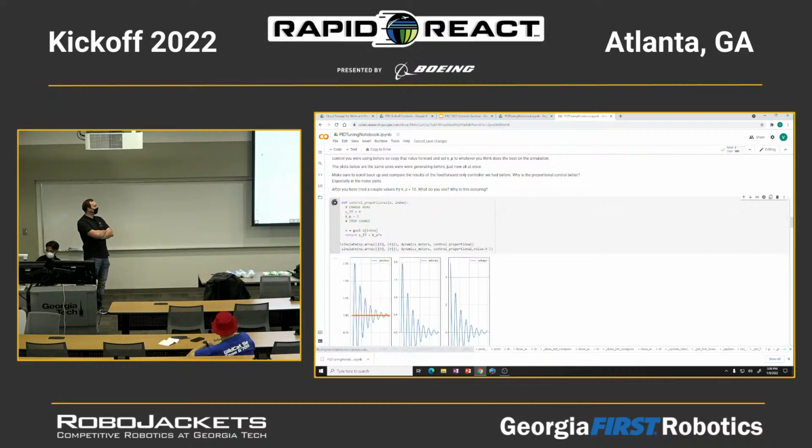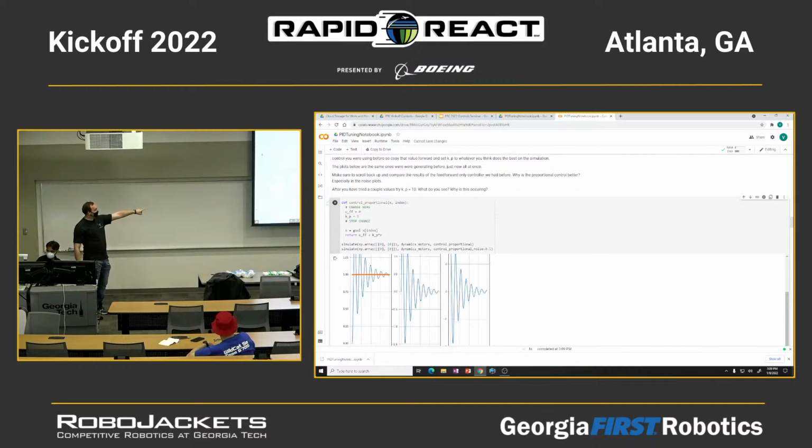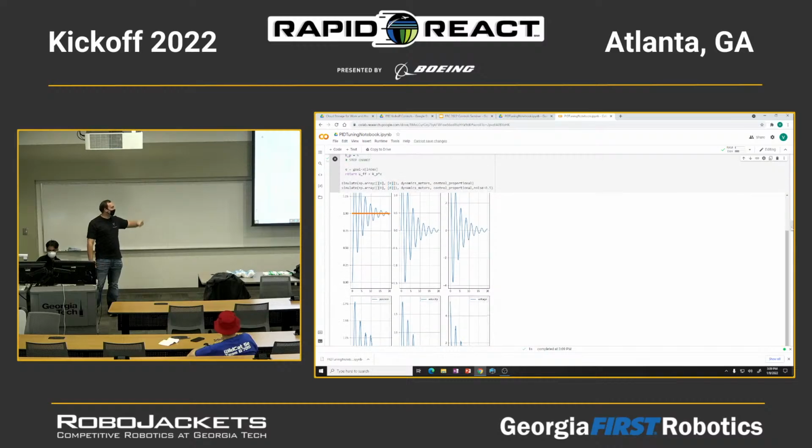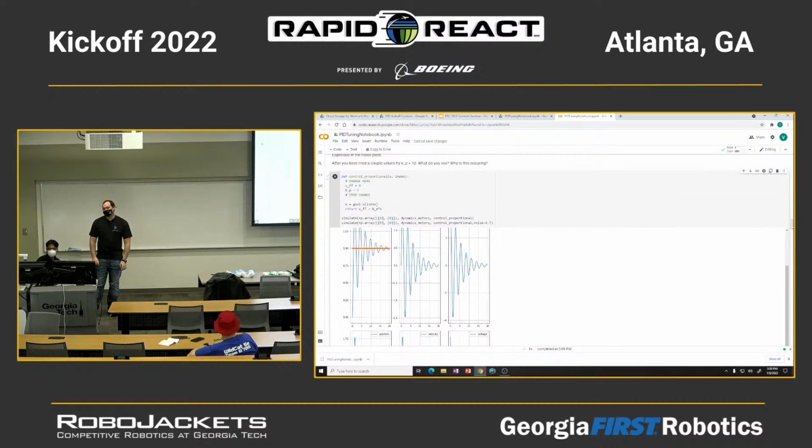And then we hit run, what we see now is our oscillation is increasing. It's stabilizing faster though. So maybe this is what we want. Maybe this is the behavior we're seeking. I mean, probably not. I don't think anyone wants to see the robot go like this, but it'd be a lot of fun. That's cool. So P controllers are pretty good, but hard to stabilize, right? This is the basic idea of P.